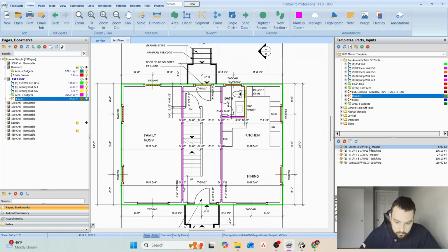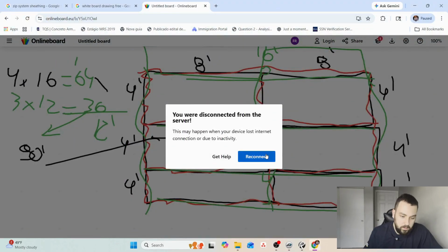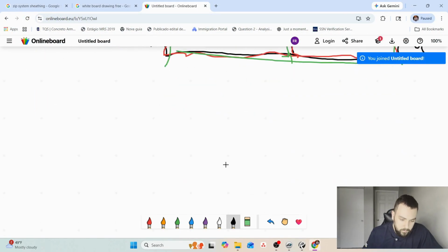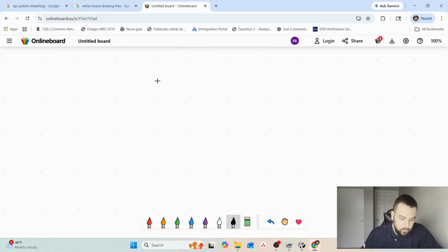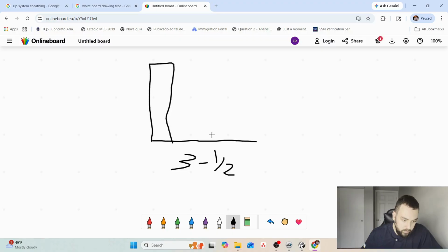I just checked the material, so it's a double 2x10. To be honest, in my experience, doubles work for 2x4 exterior walls, but for 2x6s, to make it flush we need 3 for drywall. So there's a 2x4 wall, which is 3.5.